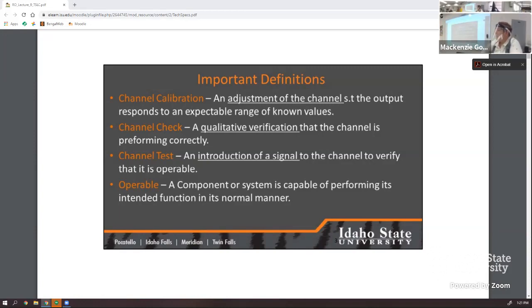Okay, and do we put the channel check and the test and calibration results in our operator logs? Most of the time with channel checks, they're going to give you a checklist, right? So we talked about that as one of the control documents. As part of the procedure, it's going to say either complete pre-startup checklist or perform this step and record the result in your pre-startup checklist, right? Either language does the same thing. And then you're going to take your pre-startup checklist and you're going to have to get the SRO to sign off that you can start operating, right?